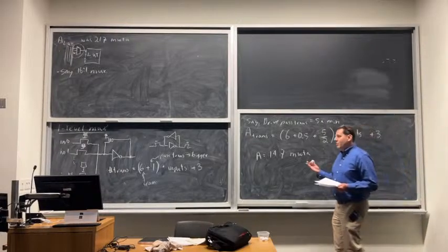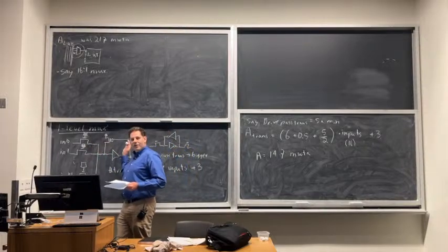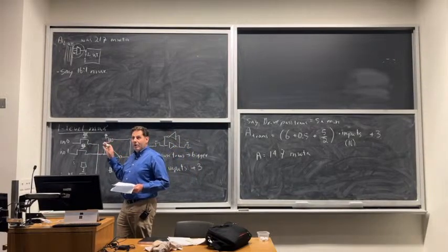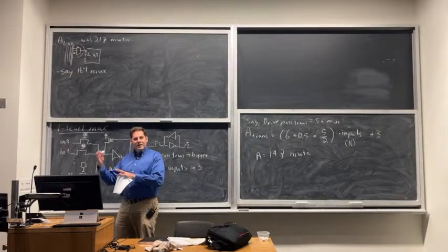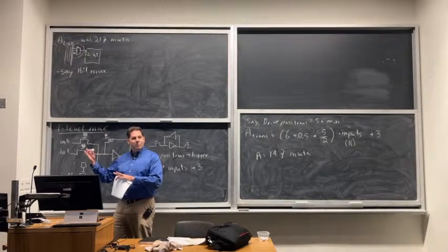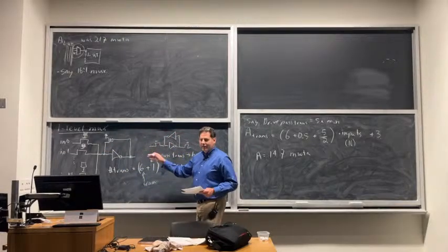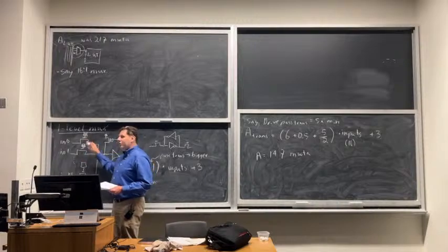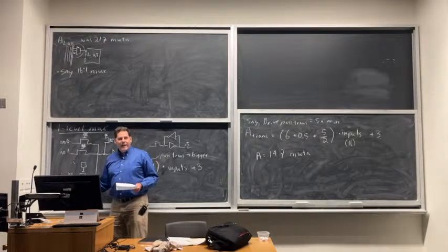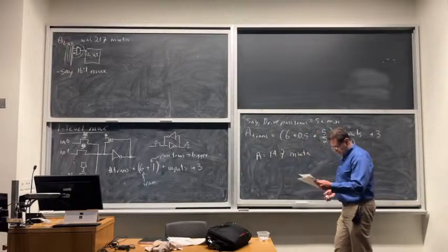So think of the lookup table. In the lookup table, we used essentially a binary tree of pass gates. And that was important in the lookup table because we needed each input to control one level in that big tree. We could build a tree like that here, but control it, instead of with the inputs to a lookup table, with SRAM cells. And that actually minimizes the number of SRAM cells we need. So let me show you that one.